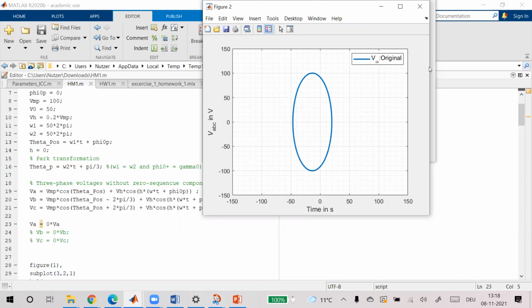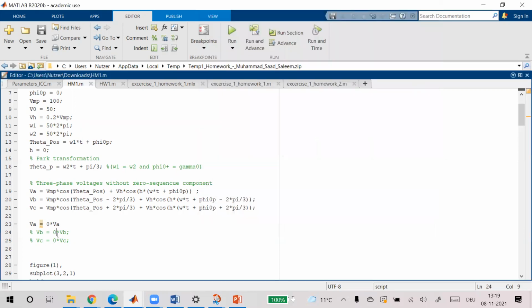So you have to know these things, and in the exam for sure we can give the shape, and then we can ask you to tell us which fault it is. So which fault is it? Is it symmetrical or unsymmetrical? Unsymmetrical, because there is just a fault in one place. And which phase do we have the fault in? The phase A.